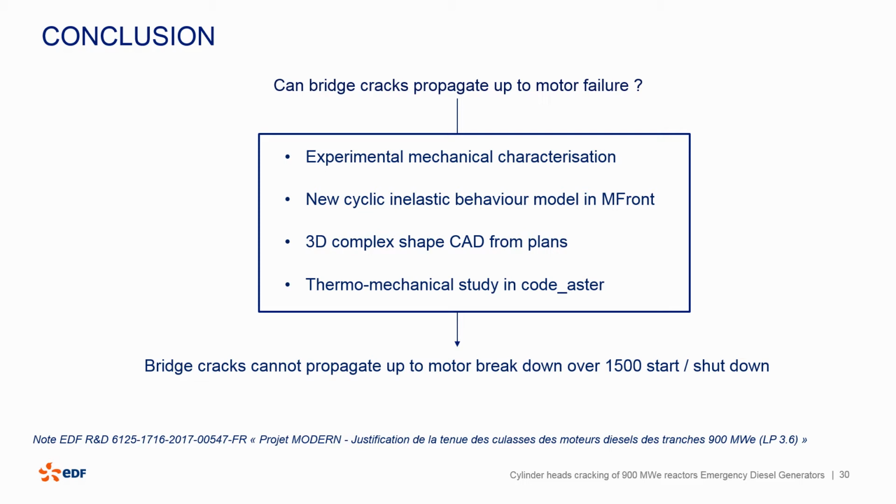So at the end, if I go into more detail, you specify to the software where you want to have your crack. It will extract a volume around that crack. You bring it to the software. The software will remesh that zone with the discontinuity inside of it, and then it brings it back to the original mesh, and you glue it back to the part in which you're working. At the end, you get the exact same group of nodes, same group of elements, but you also have new ones around the crack. If you do some crack propagation analysis or just crack stability problems, you need to know where your front is, so you have all the groups already made for you.